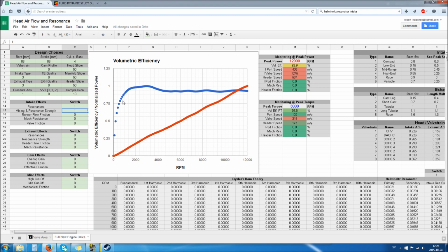And this effect we can see right here right now. That is for speeds below 70 meters per second in an engine, around-ish. Normally an estimate for optimal airflows is 70 to 80 meters a second. With that in mind, I just modeled an effect which kind of kills it for slower airflows. And that same effect is on the exhaust side as well, which we are going to take a look at later. But now, of course, if you have a longer runner, the flow will be more limited.